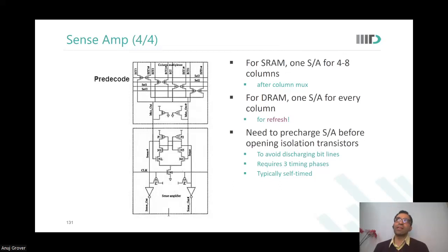So let us look at it like this. Let us say for an SRAM, the area of the array is 9, area of the periphery is 1. Total area is 10. For a DRAM, that 9 would shrink to, let us say, 2. Let us say you made the periphery 3 times bigger, from 1 to 3. What happened? Total area is now 5. Comparatively, half the area, right?